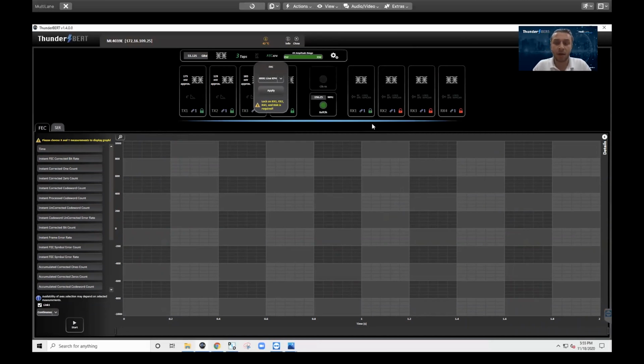So that one lock indicator means that I have grouped all 4 electrical channels into a single interleaved, striped, if you will, FEC link, a single 400 gig FEC link with KP4 and Reed-Solomon 544 code words. So now that we remember we had that 1e-6 pre-FEC bit error rate, now we're going to see what happens with the post-FEC story. We've added that FEC. Now the signal is encoded correctly.